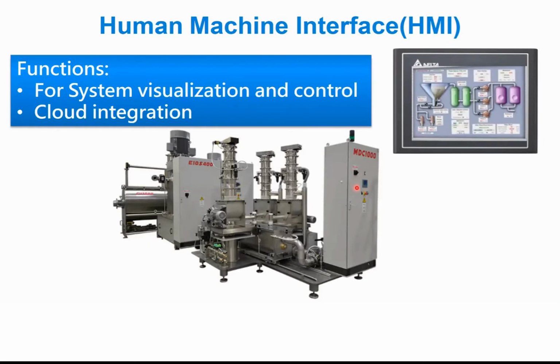So it's quite accessible. It's local. And then the other one, which is quite scalable, is SCADA. SCADA is remote. SCADA is also for visualization. Most times you have the SCADA system in the machine room. So when you have a series of machines, you want to visualize and control them, then you need a SCADA system, which you can have in the machine room.